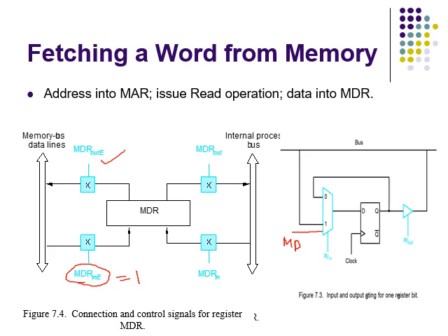Typically, a cache will respond to a memory read request in one clock cycle. However, when a cache miss occurs, the request is forwarded to main memory, which introduces a delay of several clock cycles. A read or write request may also be intended for a register in a memory mapped I/O device. Such I/O registers are not cached, so their access always takes a number of clock cycles.